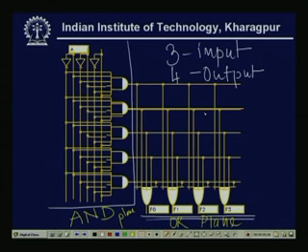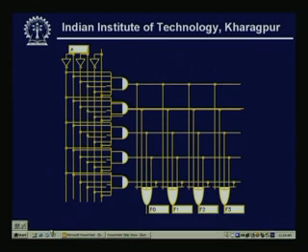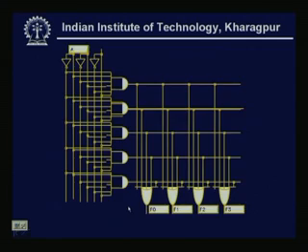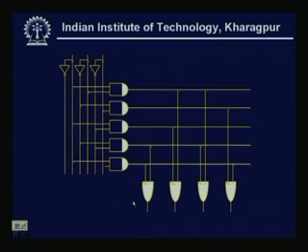That variable means that I can get any product terms from this 3-input variable, and any 4 outputs from here. But if it is 5 outputs or 6 outputs, then I can add some more in the OR plane. I can add say F4, I can add F5 like that. Okay. Now, the example we have discussed, it is more concrete.